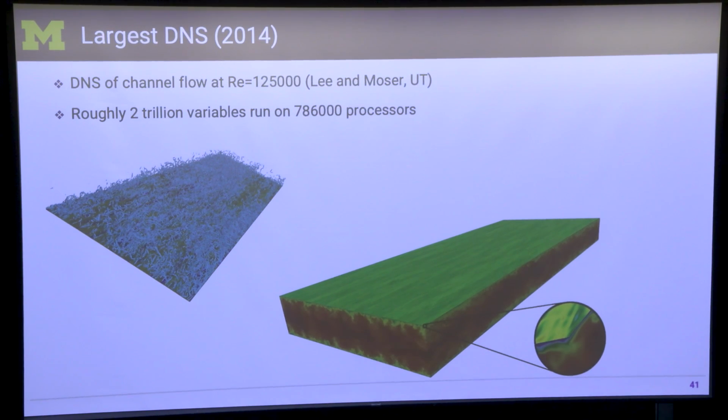So we're still 2 orders of magnitude difference in Reynolds number from what is possible. 2 orders of magnitude difference in Reynolds number means that it's cube of that, right? So we need 1 million times more powerful machine before we can simulate any of these geometries, okay? It took 20 years for this million increase in compute power. Maybe it'll take faster the next 20 years, who knows? But it's still a bit away. Okay? So it's not easy to simulate this.